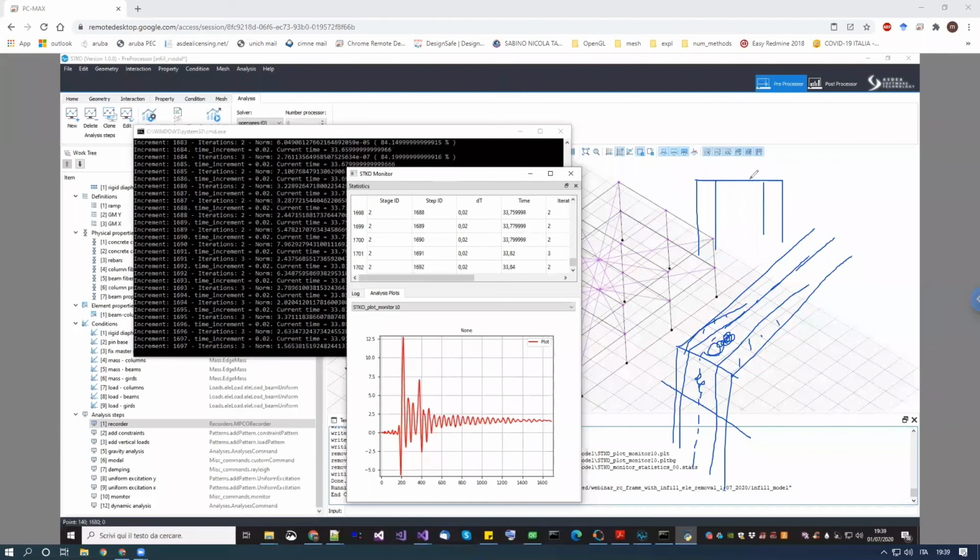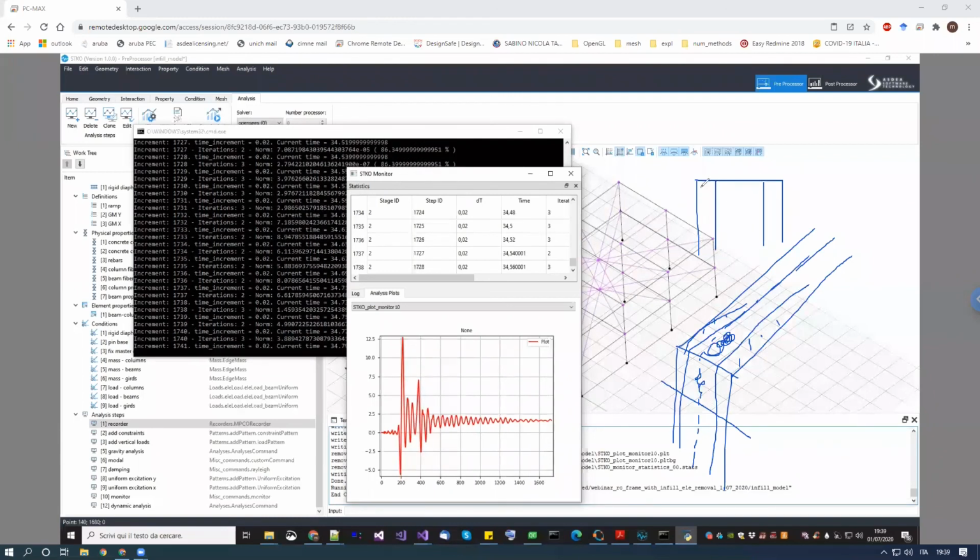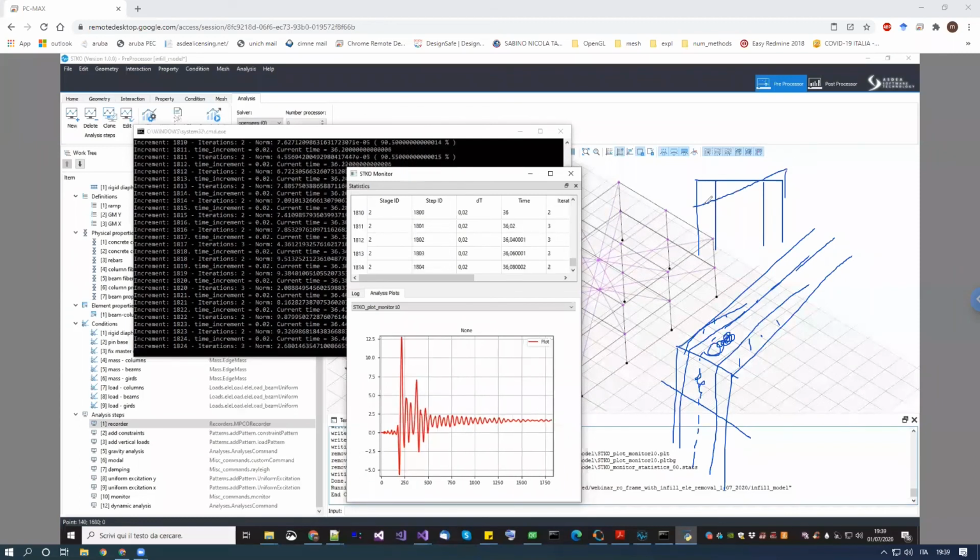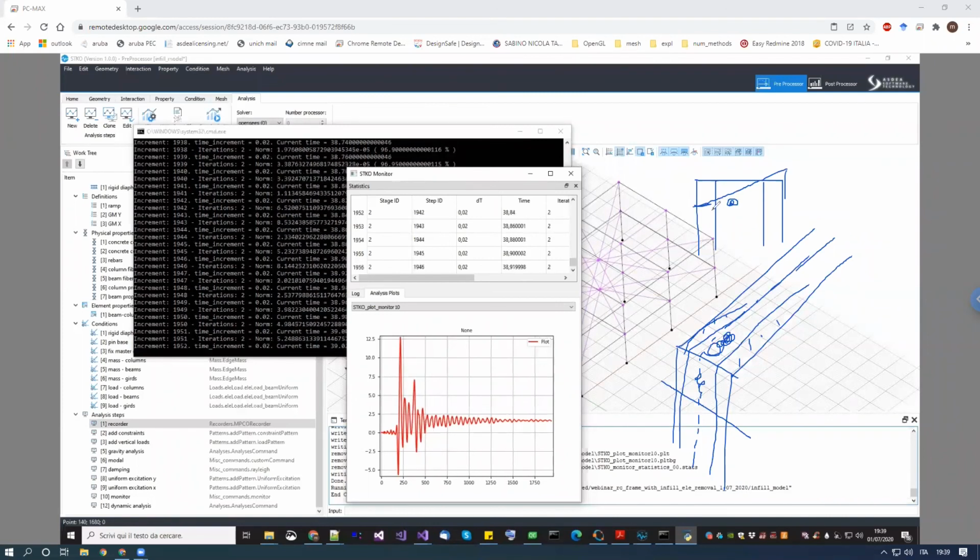This is the undeformed shape, okay? What the shell does is that if it bends, the assumption is that the face will remain flat. So it is fine if this one has more or less the same stiffness as this, but if this one is very soft with respect to the other, you will have some deformation like this one. And this is not available in any shell. Any shell is called first order shear deformation theory, because they assume that the shear deformation is constant because the section remains flat.